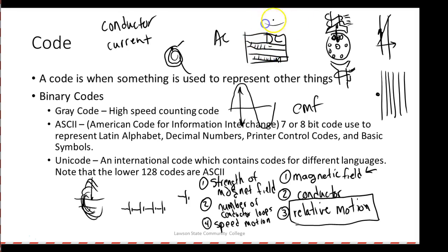So when I start it off, this is basically like a short circuit, guys, and it's going to induce a lot of voltage into the rotor, right? You understand? Which is going to cause a lot of current to flow. We have a real strong rotor current. We have a strong stator current. So these motors create a lot of torque when you do what? When you start them.